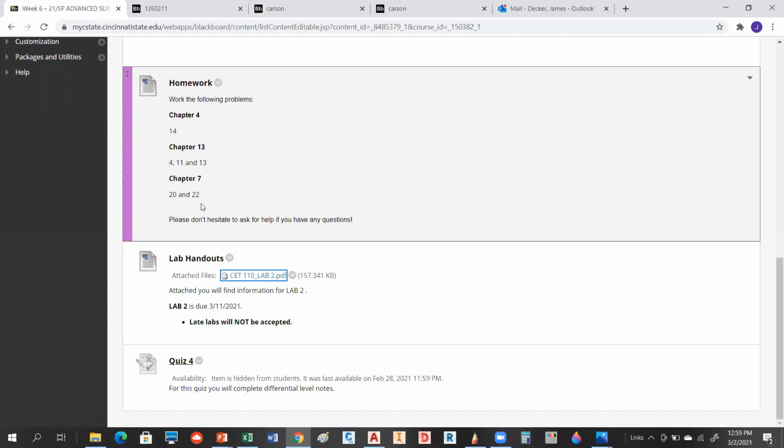And you're not really doing any measurement. You're just basically laying one tape next to the other, and you're saying, hey, this is out by 1/100 of a foot. And that's really how they calibrate them anyway, essentially. It's just comparing one steel tape to another steel tape. Okay, so yeah, that's a good observation there, right?